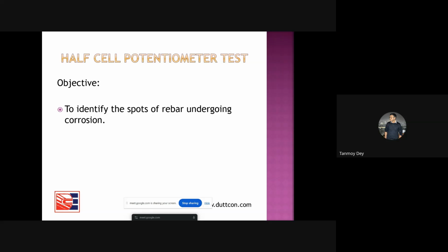We have seen in so many cases, more than 500 we are getting. So that is creating too much corrosion. That particular TMT bar has no strength. We have to replace it, or another method of retrofitting is to be suggested.